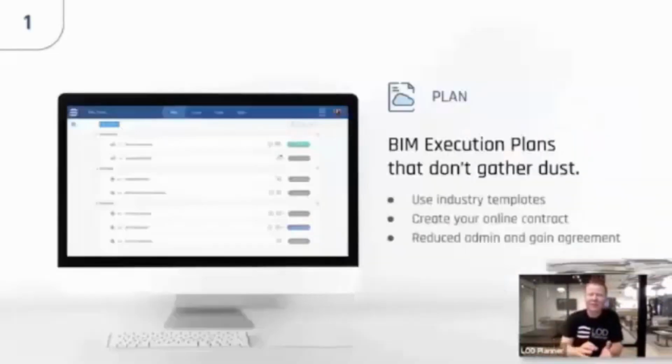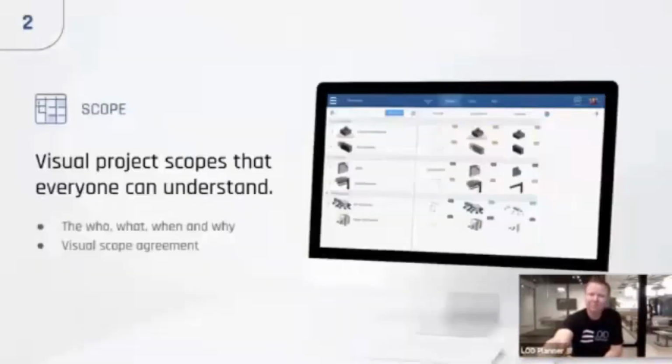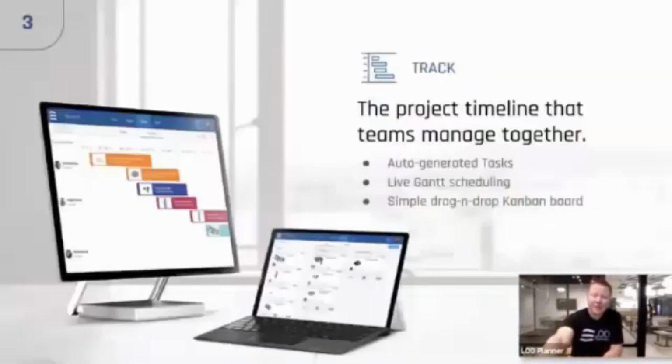So the plan, BIM execution plans, we'll talk in depth about these, but being able to create something from templates to communicate with the team exactly what the workflows are going to be. How are you going to run coordination? Who is going to be involved in the decision making about BIM uses? Who is going to be part of the team and what are their roles going to be? There's a lot of really, really important information that needs to be captured in a BIM execution plan. The scoping is all about understanding who needs to do what at what point in time and agreeing on that, the who, the what, the when, and the why in a visual way. And then the tracking is about controlling the tasks that you've just created.